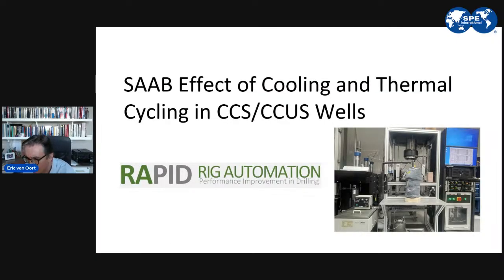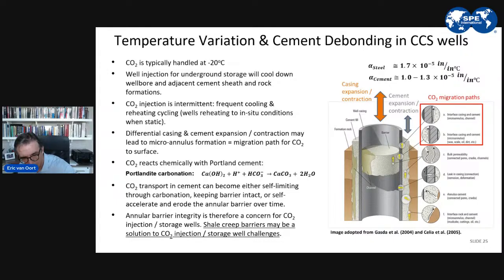I wanted to show you these results on the carbon storage test that we've done. And those tests were basically brought to us by Equinor, who are looking at alternative barrier solutions for their carbon storage wells. And if you know something about carbon storage, you know that CO2, liquid CO2, is pretty cold. It's typically handled at -20 degrees centigrade. And then when you inject it into reservoirs, you get additional cooling from what is known as the Joule-Thomson effect. So you could go even beyond that -20 degrees centigrade.